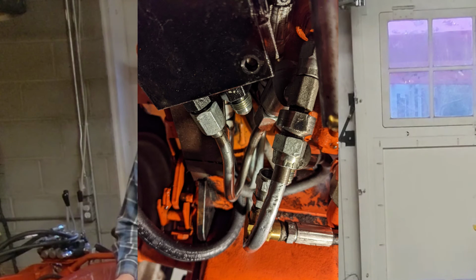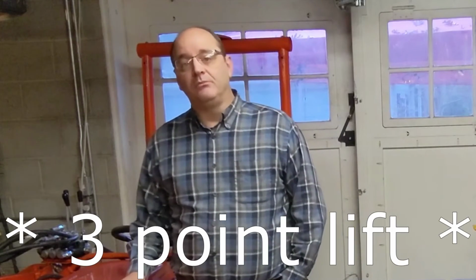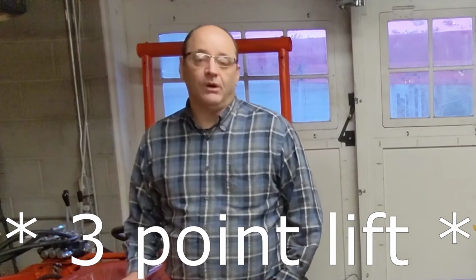Time for a leak, function, and pressure test. First of all, there were no leaks. That's good news. Secondly, the tractor does drive, and both the deck and the PTO lift do go up and down. Then I installed the loader valve and rigged up the pressure gauge again, and with the engine running, I gingerly pulled the valve handle to send the pressure to the gauge. And it was very gratifying to hear the engine bog down, hear the loader valve's pressure relief valve start tripping, and see the pressure gauge rise up to read 2,300 psi.